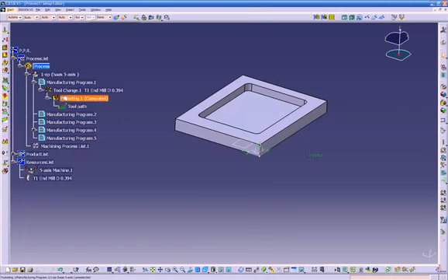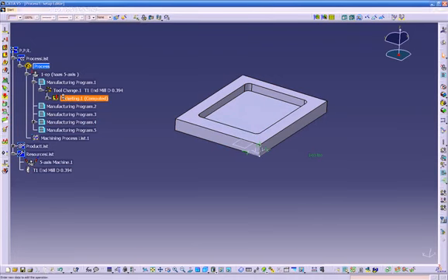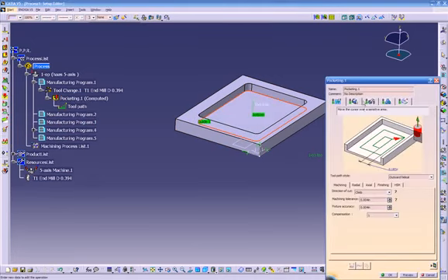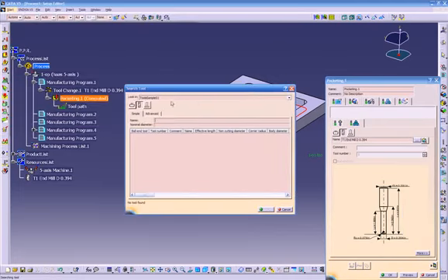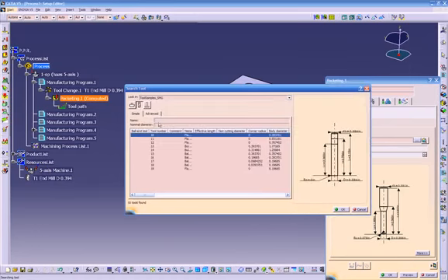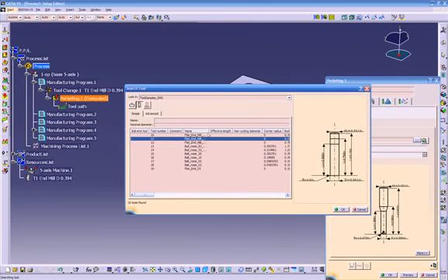So for example, right now we created this standard toolpath with the standard tool. It automatically picked up this tool on its own. It's a default tool because we've been using the sample table. So let's go back into the pocketing. Let's go to the tools and let's see what kind of tools we're using over here. So we can click here and it's telling us that we use tools sample 01. We can switch this and then see, we get different kinds of tools in here.